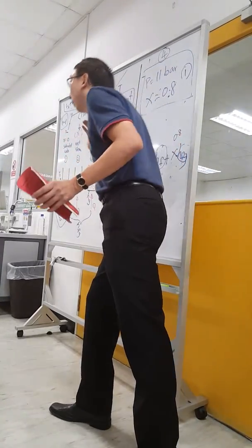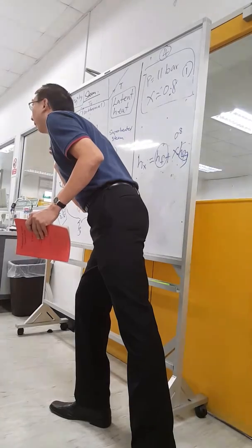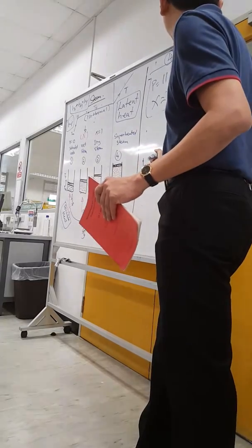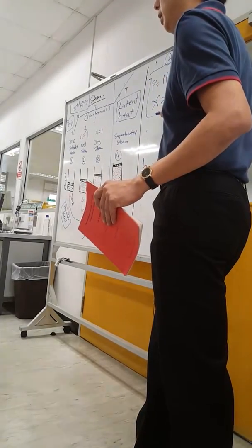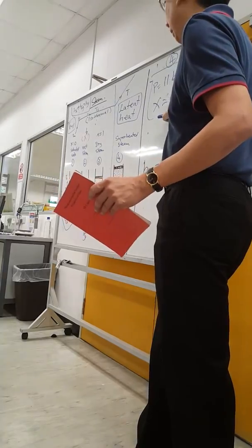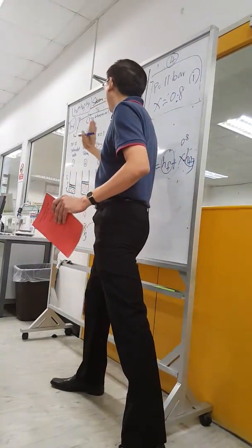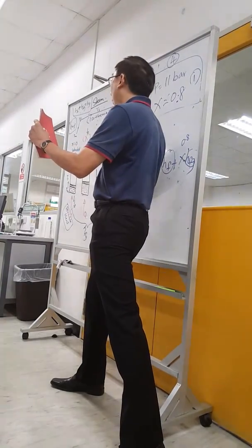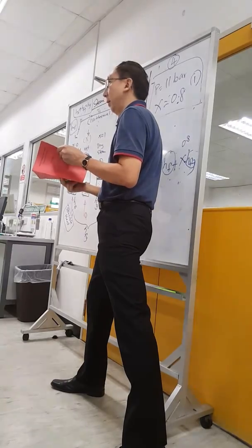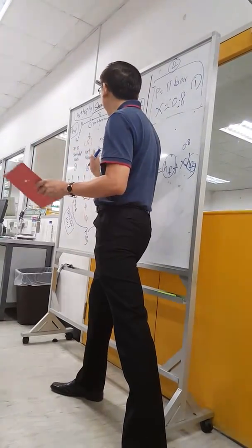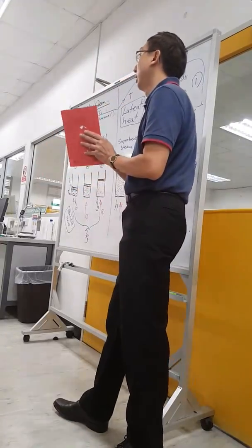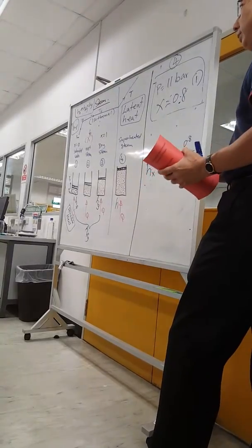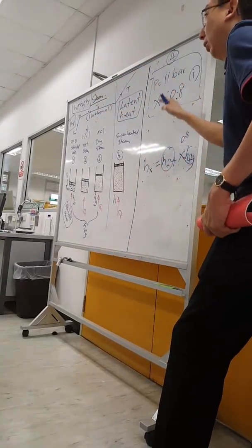Student: For the Hf from the table, do we look at the saturated water or the superheated? Saturated water, so you look at saturated. All these over here, 1, 2, and 3, are under saturated water and steam. Only this one, you go into superheat. So very simple: the first 3 are all on saturated water and steam, and then this one, superheat.